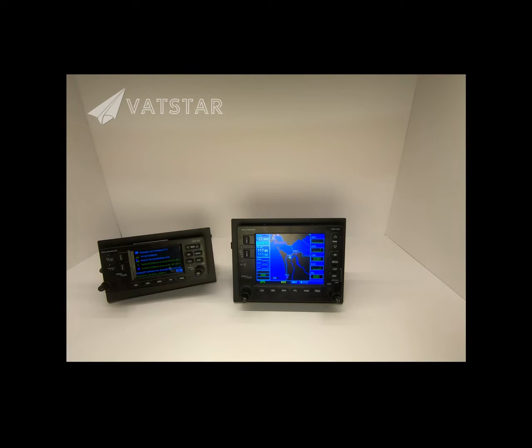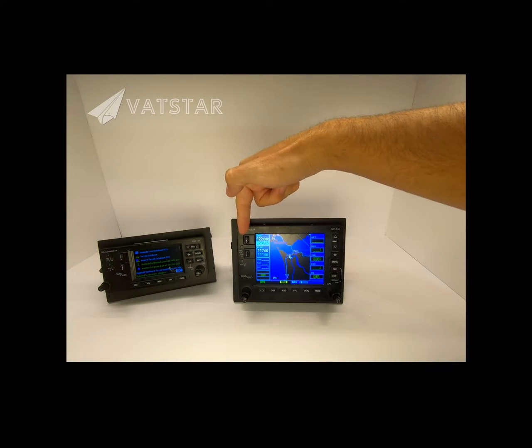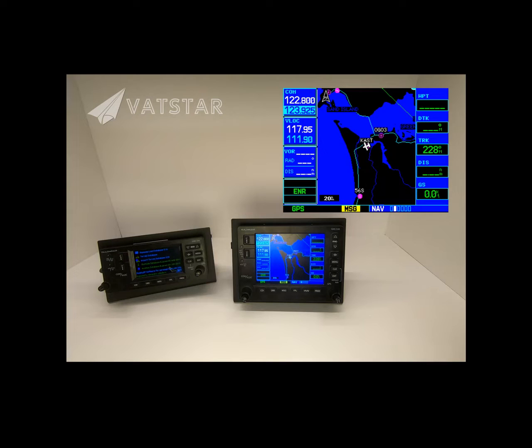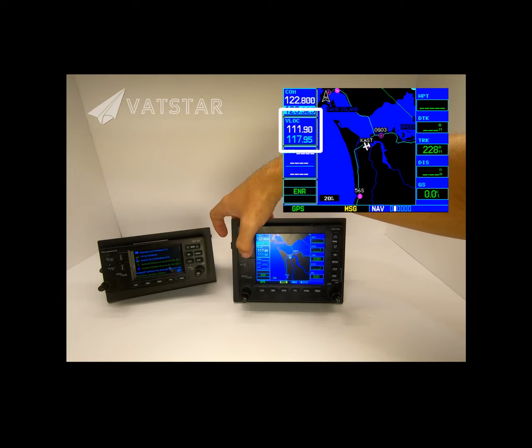I'm gonna go from left to right, from up down, right? So I'm gonna start in the top, work my way down, and then work my way up, kind of thing. So first one is very easy. You have this button right here, and that is to change your comms channel frequency, right, from standby to active. So you just press that from 122.8 to 123.925. You just do that to switch that. Same thing goes for the V-Lock one. You just press it to switch them.